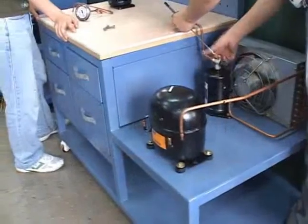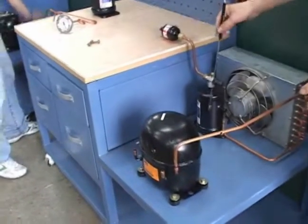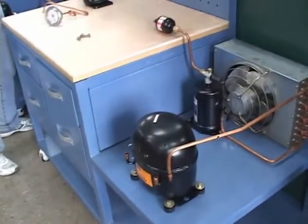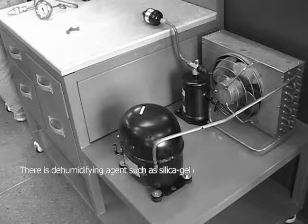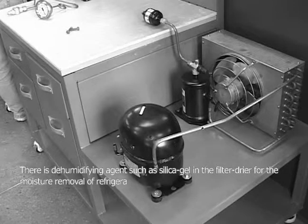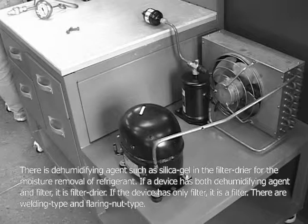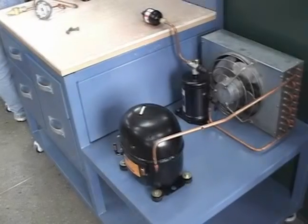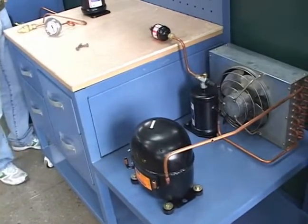Now we will connect the filter dryer. The filter dryer consists of a dryer and a filter. The filter removes the impurities in the refrigerating system that may have been generated during welding work. It also removes moisture in the refrigerant gas. There is a dehumidifying agent, such as silica gel, in the filter dryer for the moisture removal of refrigerant. If a device has both dehumidifying agent and filter, it is a filter dryer. If the device has only a filter, it is a filter. There are welding type and flaring nut type. Here, we use the flaring nut type for reuse later. Then the piping at condenser discharge and filter dryer will be completed.